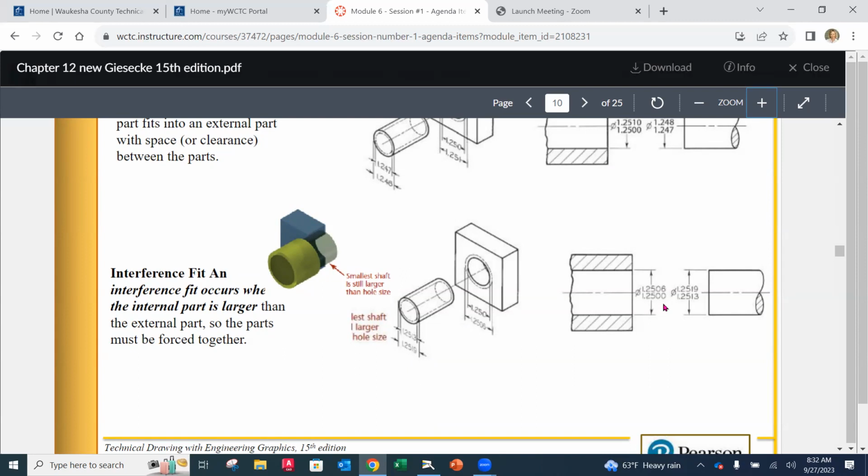I worked for a company where if we had anything other than the title block tolerance, we had to put the limit dimensions on it. This eliminated anybody making any mental math errors, okay? Because they can happen. That's going to be an induction of a human error. So whenever possible, if you deviate from the title block, it's always a good idea. Limits are just nice. Nobody has to do any mental math in their head. So anyway, these are limit dimensions on both, which is good.